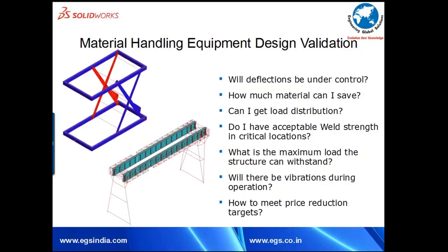Because the system became more flexible, the life increased, the operating members' bill of quantities and bill of materials and their weight reduced, the bearings became smaller, the hydraulic actuator became small, the reservoir had to contain less oil, the heating of the reservoir as a result of the oil being pumped is lesser, the pumping of the oil became lesser, the cycle time of operation became larger, and the warranty exceeded the 5 years. So it is a win-win situation where you are looking at design for cost when you are looking through the prism of design for life.